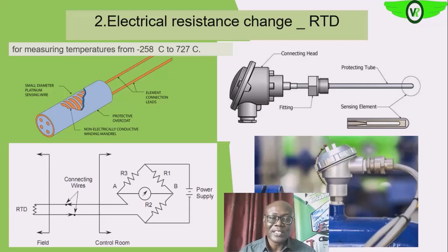So you see that the RTD, or the resistance temperature detector, is connected to a Wheatstone bridge. Are we seeing it? So at rest, that is at zero temperature, it is connected so that the output from here will be 0. Okay, so as the temperature is changing from 0, of course, the balance of the Wheatstone bridge will be altered because the resistance of the RTD will change. So let's assume that it's a positive coefficient RTD.